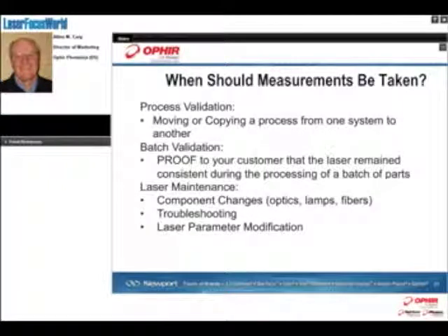Sometimes you'll have a laser that's not performing properly. You need to measure your laser in order to troubleshoot what's going on with that laser. And any time you need to modify the laser parameters, change pulse width or change power output, that kind of thing, you need to use the equipment to make sure that those changes to the laser parameters had a good effect.